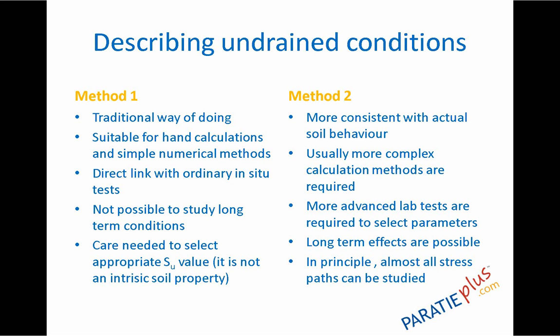Of course, in this method, it's very difficult to study long-term conditions because we cannot know directly how the pore pressure evolved during unloading, during undrained parts. And also, it is very important to select an appropriate value for undrained shear strength. That is not a material parameter, but something more complex, and we will discuss it later.